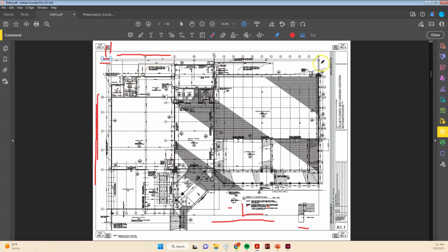The outside one will tell us the overall length of the building, and as we move in to further strings, it'll tell us where the changes in geometry are. I'm quite sure there are dimension strings describing every change in the wall there. And similarly down here, we'd have an overall string, and then wherever there's a change, we would expect to see dimensions.